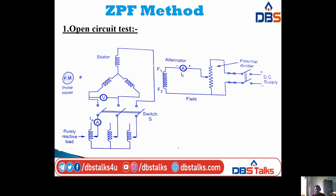Next we have the field winding. The field winding consists of one ammeter, which is used to measure the field current. This ammeter is connected to the field rheostat or potential divider, which is used to vary the flux. And next we are using a DC supply through the switch.